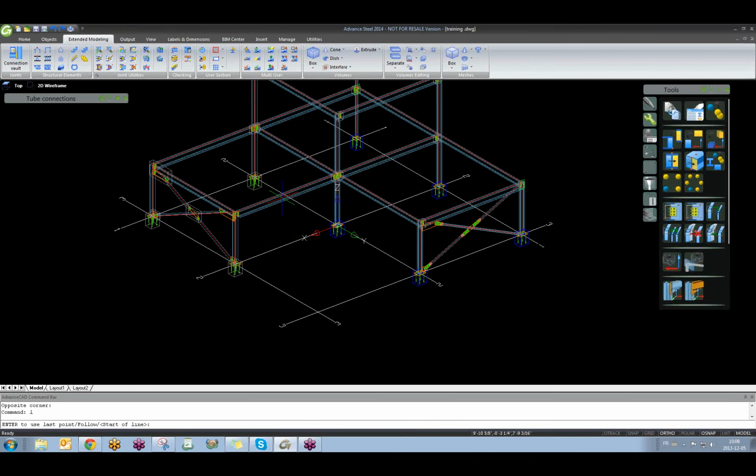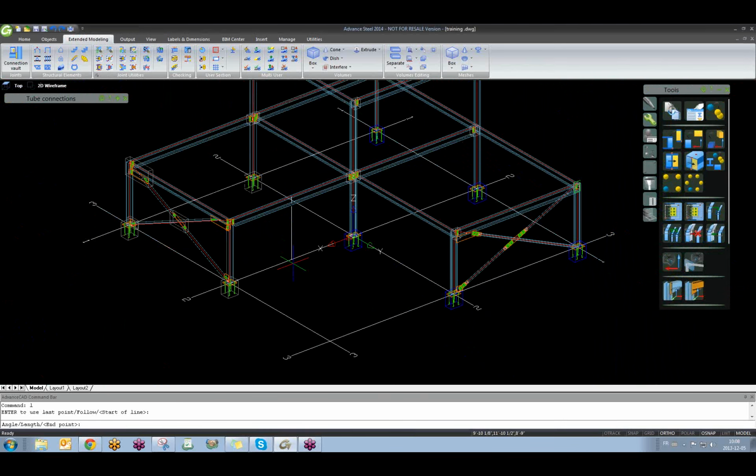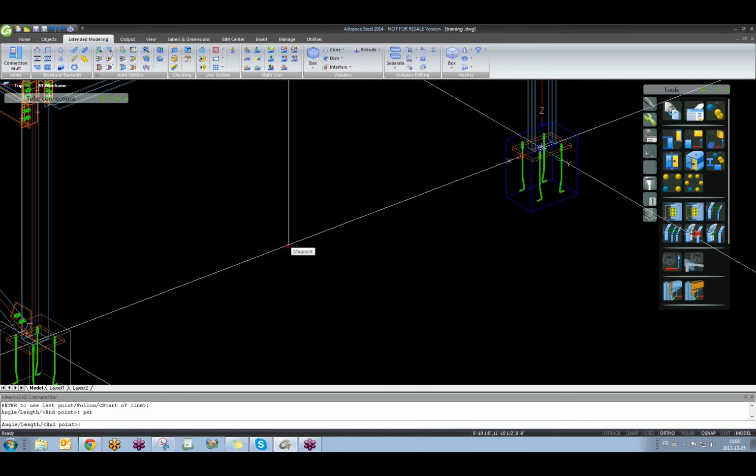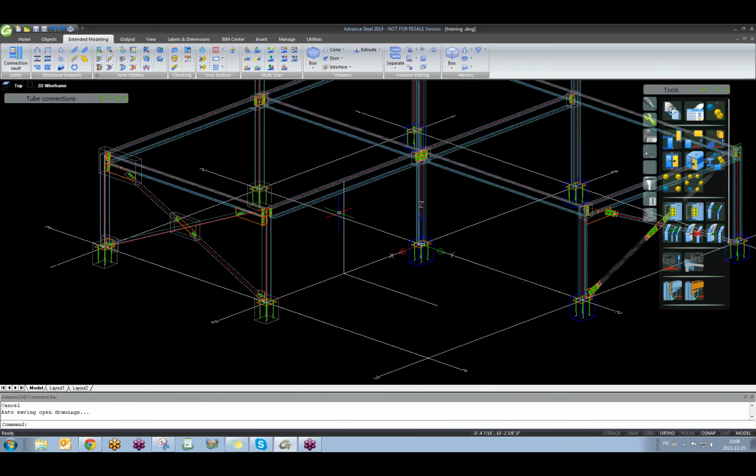I'm going to do some from here, here, and now just specify your widths. Now I'm just picking some values, but while doing your stairs, you should have specific values. And the 2 points that you will pick to specify the height of your stairs will be the nosing points.